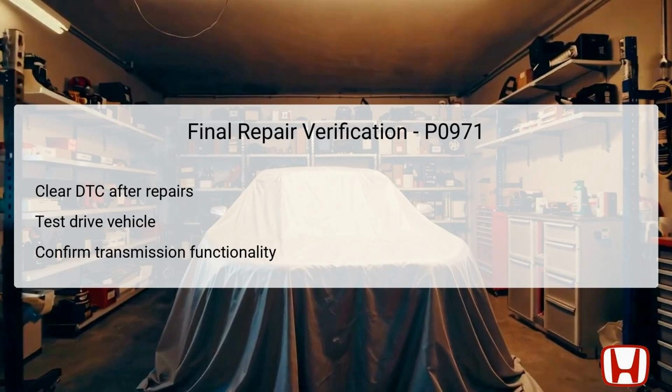Pay particular attention to the shifting behavior and responsiveness of the vehicle, ensuring no symptoms of the original error reappear. Monitor the check engine light. It should remain off if repairs were successful. This exhaustive verification process confirms that repairs were performed accurately and the vehicle returns to optimal performance levels.